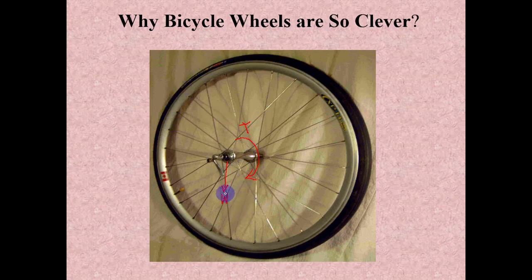When the load W is applied at this part of the wheel, it will not be distributed uniformly to all the spokes. Basically, this W is concentrated on 2 to 3 spokes located in this zone very near to the ground.